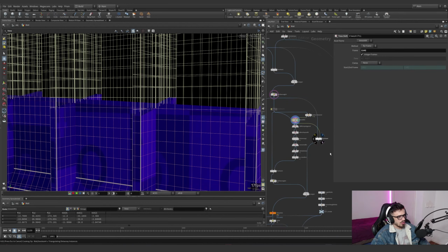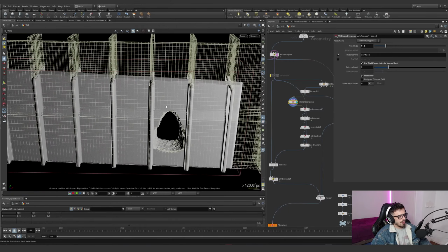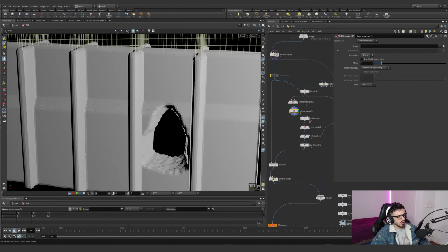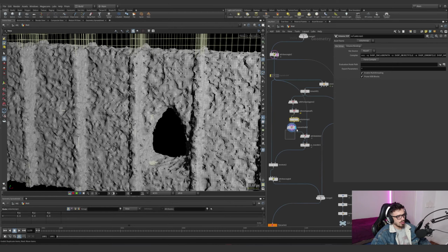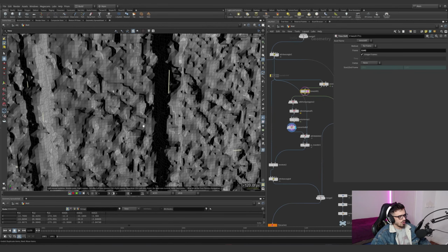We have these two separate pieces of wall. I'm having this wall, which is VDB, and I'm reshaping it to make it a little bit larger. I'm also adding a little bit of noise. This noise is just a turbulent noise with the offset set from 0 to 1 to -1 to 1, so the noise is centered. The resolution is 500,000 voxels, and I convert this to VDB. It will create a somewhat strange shape, which luckily interpenetrates with our original shape, as you can see here, here, or here.